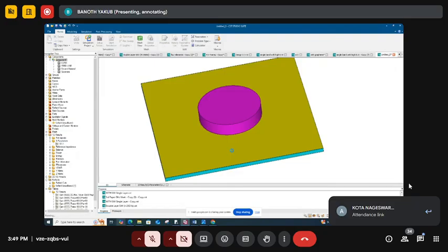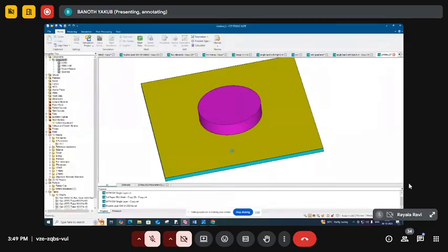If you do not do this step, the graphene material will not be shown anywhere in this CST. So before adding the graphene layer, you add this material to the material library.